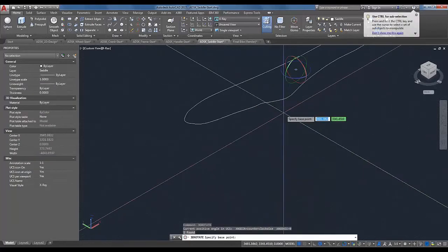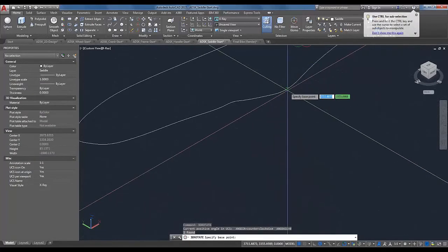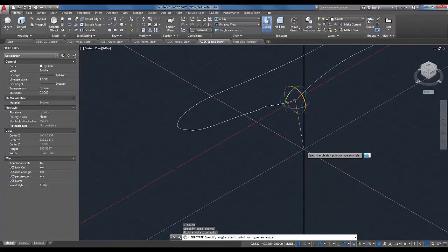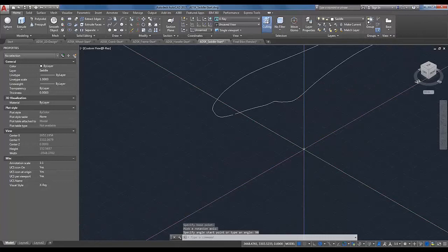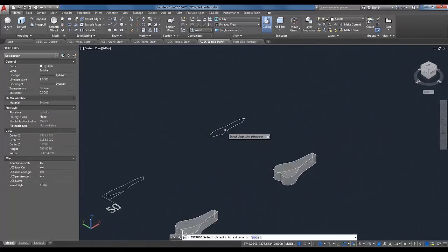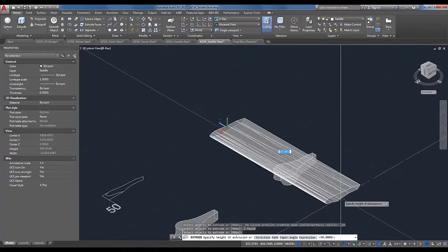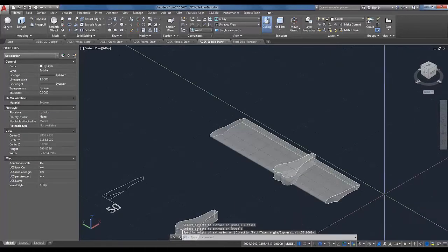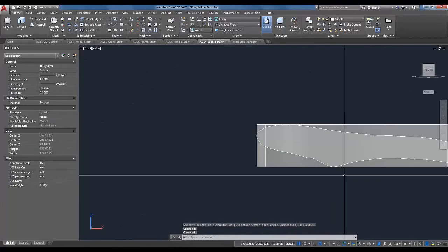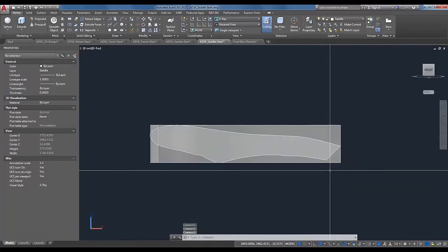There we go. And just like that frame, I want to really make sure I grab the bottom of this thing before I rotate it. I'm going to grab that one axis of rotation, go down 90 degrees. I'm going to extrude this guy clear through the saddle like that. If I go to the front view, do some QA, QC, make sure everything is looking good. Yep, we got some good overlap going on.